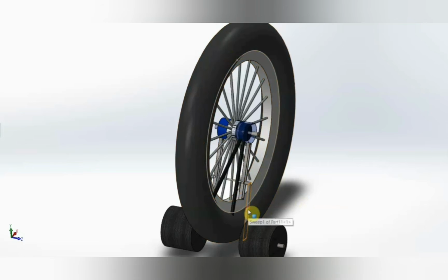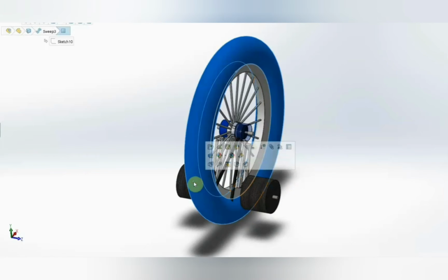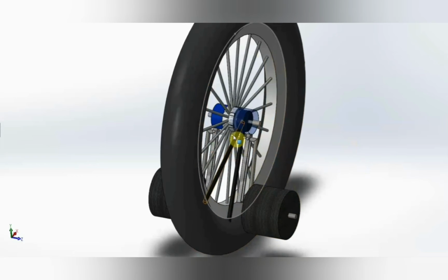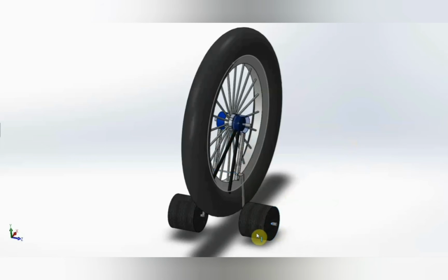There are two slider rods present on either side of the tire. These slider rods support extension rods on both sides, and these extension rods at their ends carry the additional wheels, which are going to support the vehicle in case of puncture. Initially, the additional wheels will be at the topmost position, and the main wheel will be supporting the vehicle for its running. In case of puncture, the main wheel will be inflated, which is done with the help of an application, and these additional wheels will be lowered to the lowermost position. This lowering is done manually, and it is not a tedious process, but is done by simply removing and inserting the bolts.